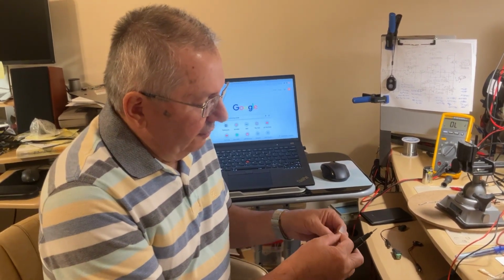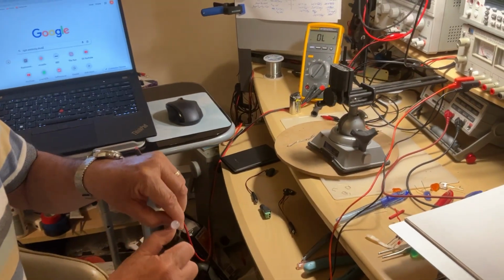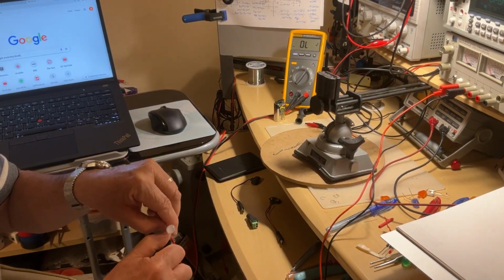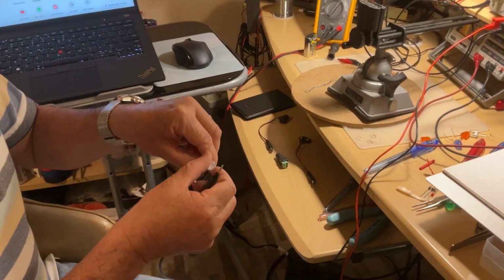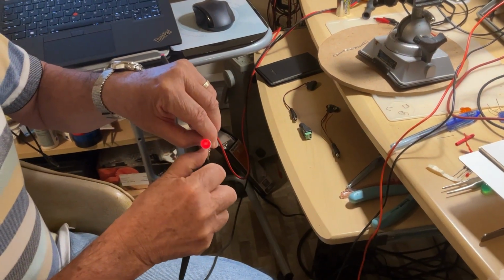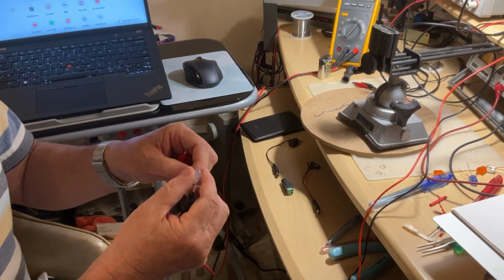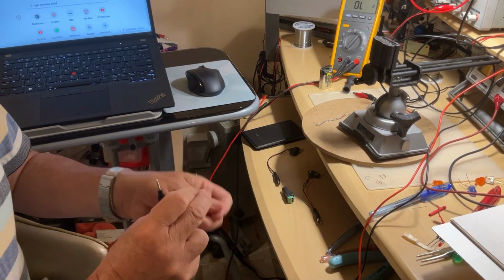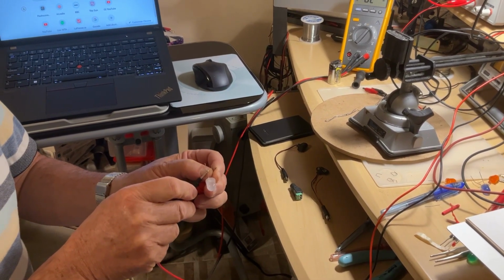For instance, if I'm using my meter to energize this diode and I just touch the terminals, you won't see anything right now because the diode does not emit light. But if I turn it the other way, now you can see the diode blinking, okay? So it does not conduct in both directions. Like in this direction, if I energize, it's not conducting.